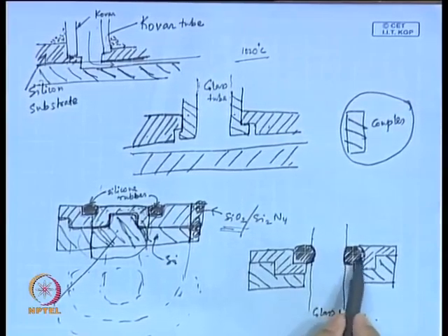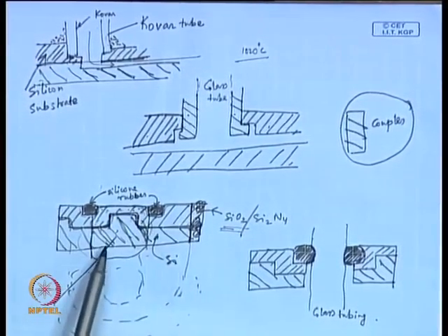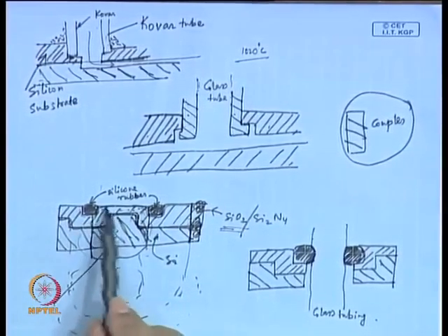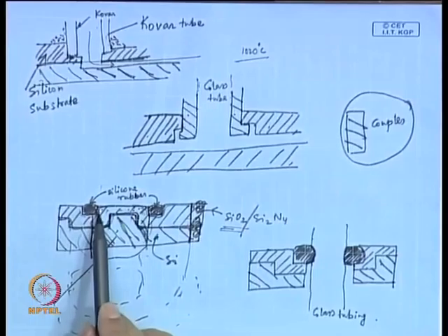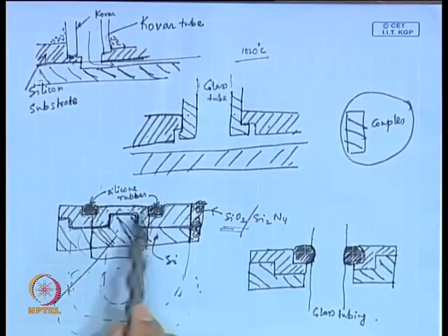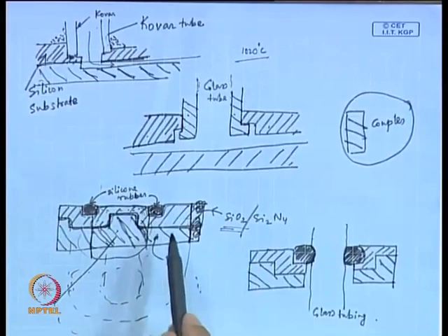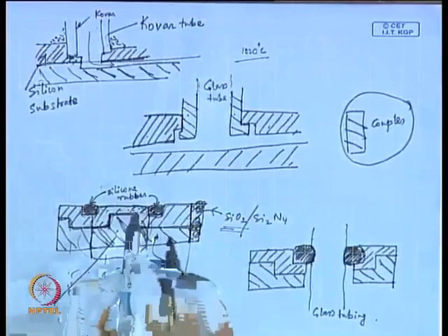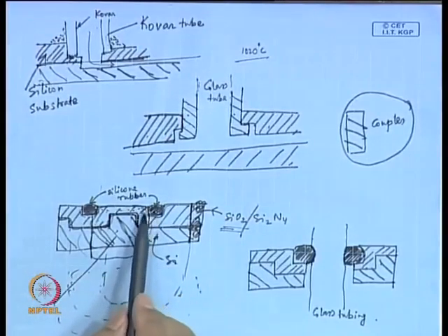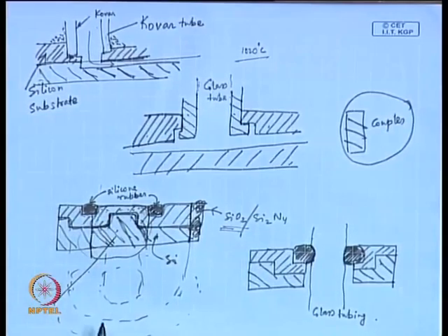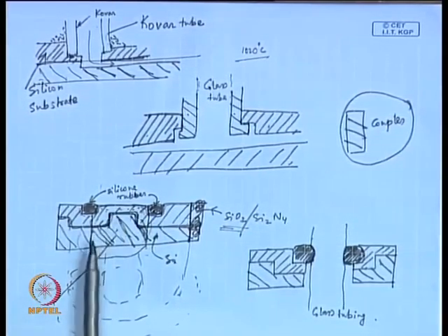So, this is the silicon wafer. You take the silicon wafer, put a layer on top, so that you form a cavity in these places, and pour in rubber which is different, squeeze it into this, which is going to act as a gasket. Then you go from the back side, first remove the silicon layer.